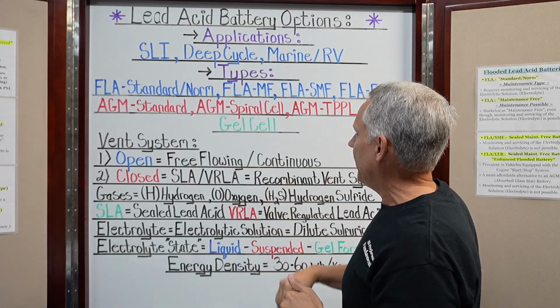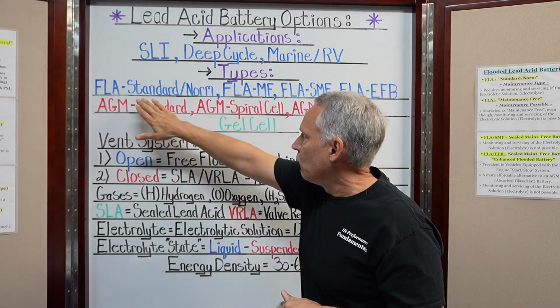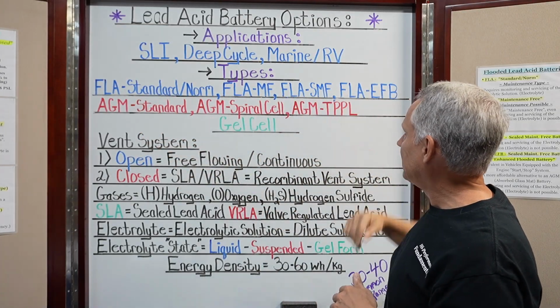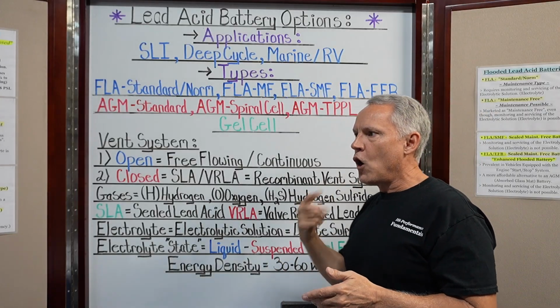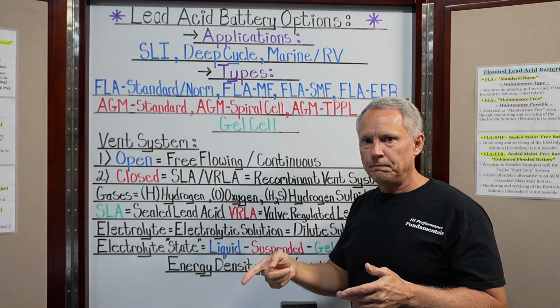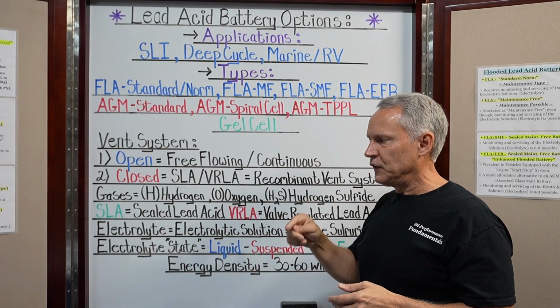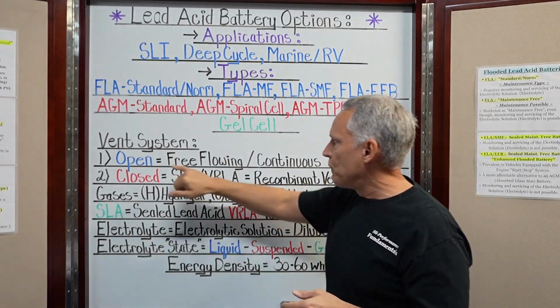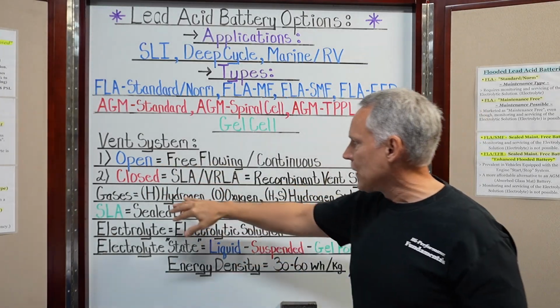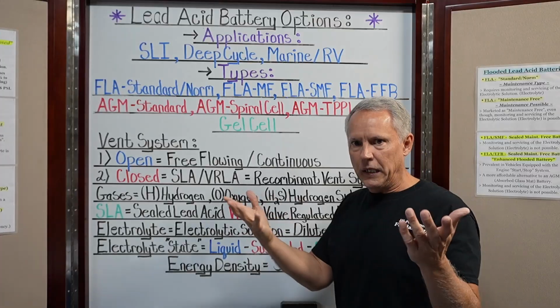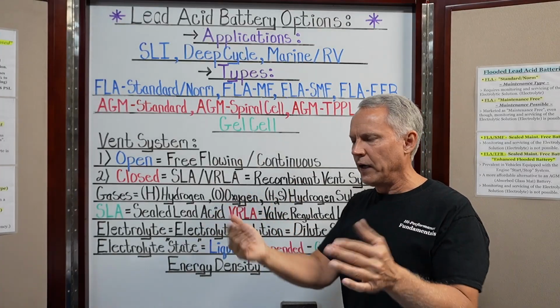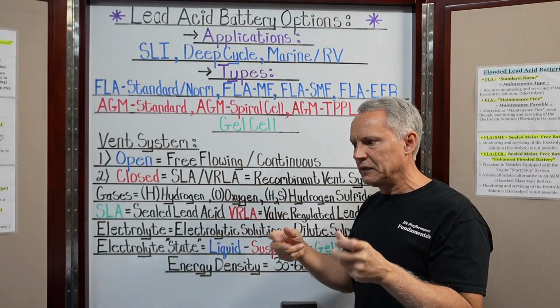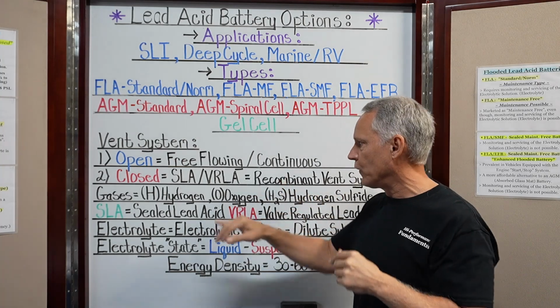So that's what we're talking about up here when we're talking about maintenance free. When they say maintenance free, they're talking about no need to service the electrolyte. Now, as I just said, since it's an open vent system and it's venting hydrogen and oxygen normally, the battery is going through chemical reaction processes, and hydrogen and oxygen gases are formed, and they're venting.